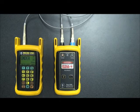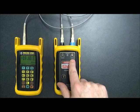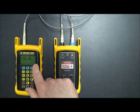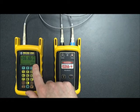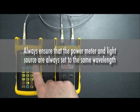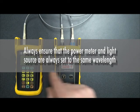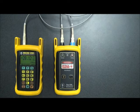So first thing we do is we press the wavelength button on the dual owl, and you can see that it switches over to 1300 nanometers. We also have to change the wavelength on the micro owl. You see it says 850 nanometers here. So we need to switch it to 1300. We can do that by pressing F3. Okay, now you can see that we have a reading of minus 20.12 here. Again, this is a good patch cable.